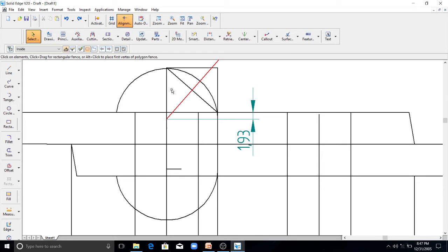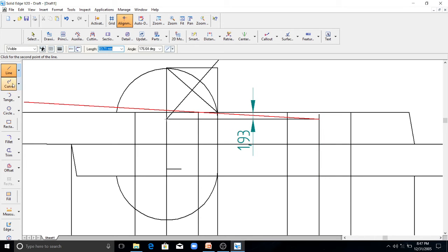Similarly, you have to draw the snap head for the second rivet. Instead of again doing the same things here, you can copy this center to this line, because these two rivets are of the same dimension. Again, no need to draw these lines again and again. So you simply copy this center here to this center here. Similarly, this center.